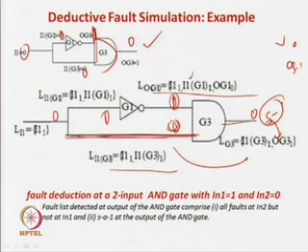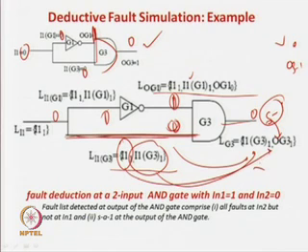We expect that I1 will be propagated here. But you see, this fault should also have been propagated here, which is not the case. Why should this fault, the stuck-at-1 at this net, be propagated? Because in an AND gate, this net value is 1. As this is a continuity, everything from here passes to here. So, the whole fault list should propagate, but there is a problem.